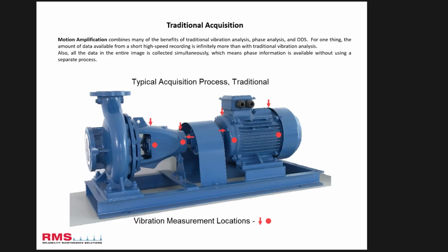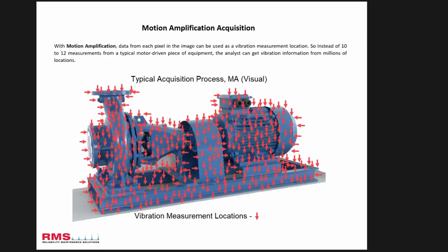Normally with accelerometers, like I said earlier with ODS, we'd put accelerometers in certain positions looking at a motor and a pump and get probably 8 channels back with a phase marker with some phase back to give us the operating deflection shape. That would be the setup we'd get normally with an 8-channel instrument. But what the camera does is each pixel is a sensor, a measurement point, so you can see how much more information we're getting back off a system like that. It's up to 2.3 million pixels on some applications, which is great resolution and great feedback, hence the images.